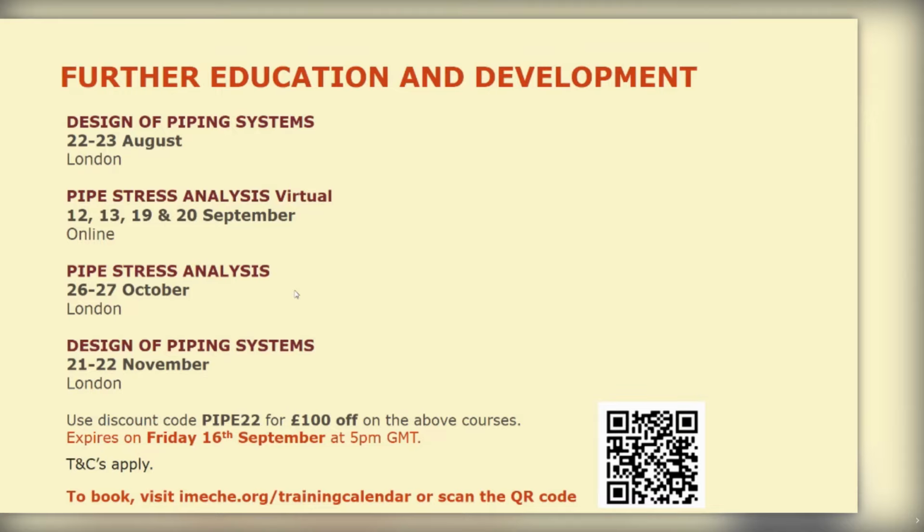Okay. Another one then quickly. This is more of a statement than a question, but we'll get your thoughts on it. No mention that elbows add significant flexibility, and piping can be configured to allow torsion, which is more flexible than pure bending. Yeah, so that's right. It's just because of the time of the webinar. So yes, as you have your different elbows, how you position them, if you allow the pipe not just to bend but to twist in 2 dimensions, that will add to flexibility. But again, if you're trying to do that type of thing, you almost certainly will have to use formal pipe stress analysis, because doing that by hand would be very complicated and probably not worth your time.